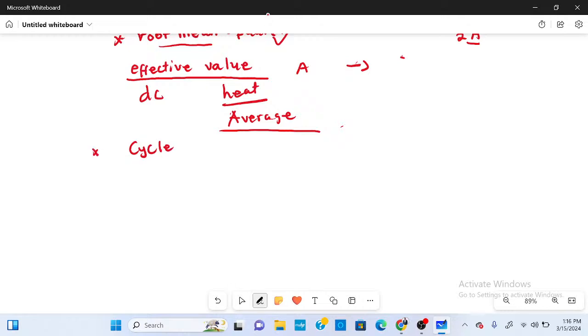After identifying your cycle, the next thing to do is determine the period. I'm going to explain these terms. Then after, you find the area of the cycle. So finally, the average value of an AC circuit is equal to the area of a cycle all over the period.